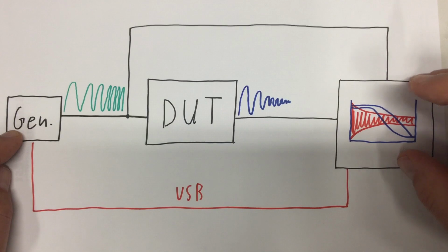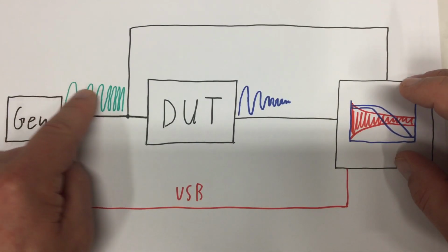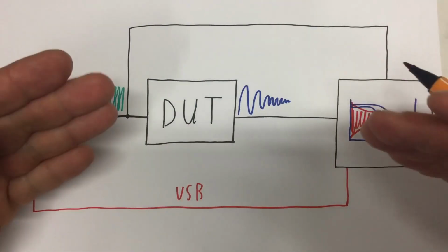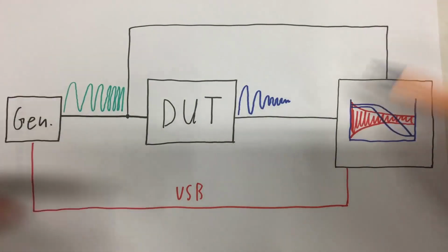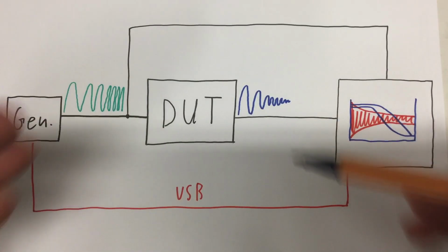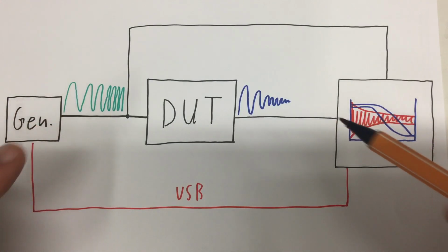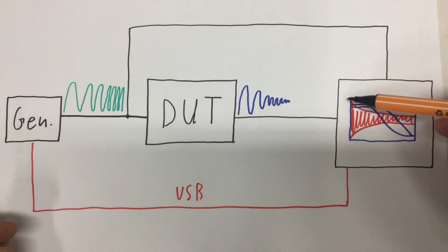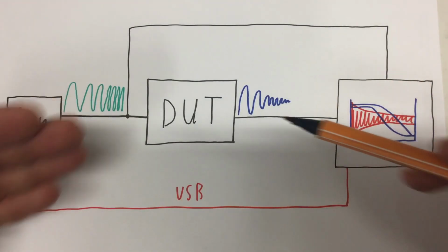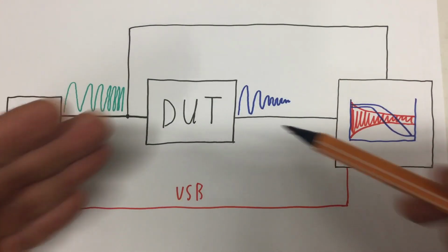So the oscilloscope has a special Bode plot mode and tells the generator which frequency to generate while it's plotting the frequency response of the DUT. And there are a whole lot of expensive, that's the problem, expensive solutions to create real Bode plots. But we really want to do it, just for the amplitude response, with the El Cheapo setup I have here on my desk. Okay, the scope is not that cheap, but the function generator is.